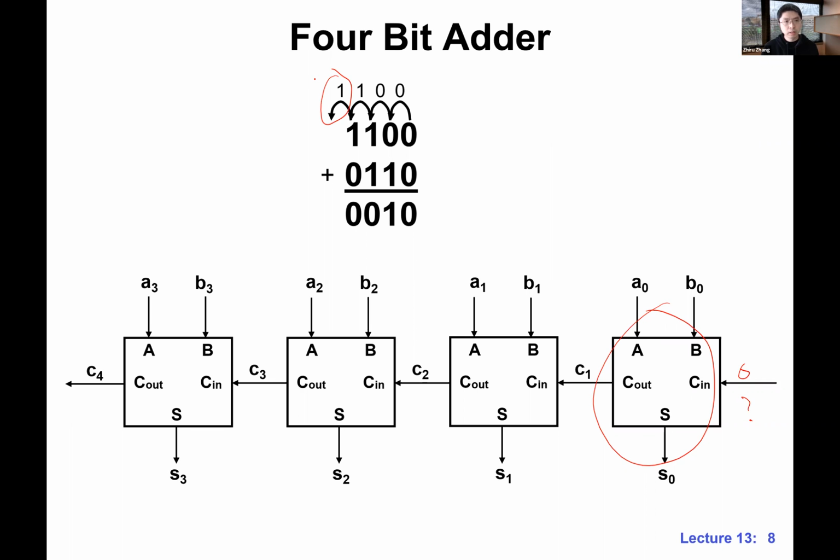Right. So yeah, good question. In many cases we do want to preserve the carry out from the MSB so that we can detect overflow. We'll talk about later how we deal with overflow. In many cases, we just need to detect it. But if this is indeed a problem, we'll let the microprocessor know. There is a certain thing called an exception that we can discuss later. For now, all we need to do is preserve that carry out in some cases so that we can detect overflow, and flag it if an overflow indeed occurs.